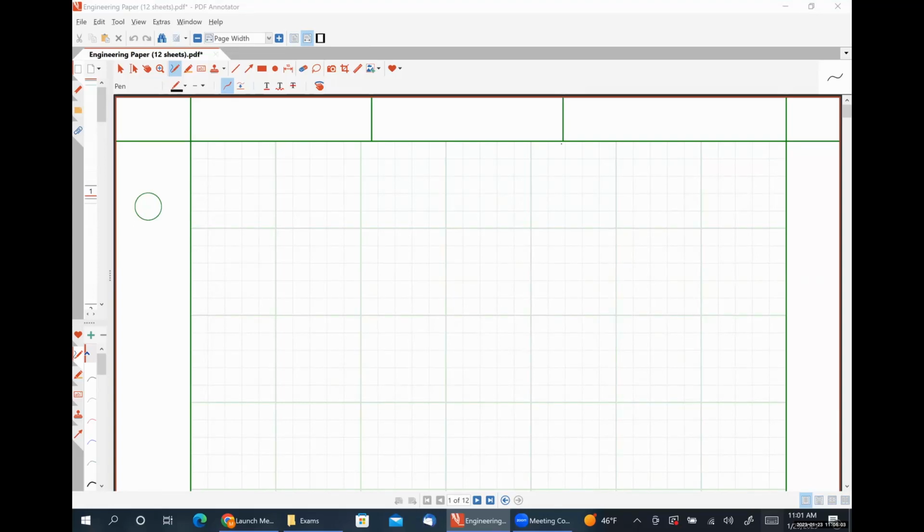All right, so today we are going to continue talking about capacitive actuation. In Friday's lecture, we focused mainly on gap tuning. And so by that, I mean our displacements were vertical to make the distance between the plates smaller.